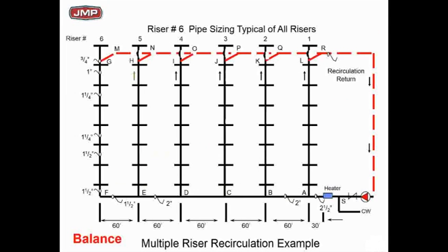So here's a piping chart for that. You see we've got risers, a water heater on the right-hand side, and a recirc pump. It's been sized, the recirc pump's plenty big, no big deal. Recirc line, but I hope you quickly realize there are no balancing valves. There are no balancing valves at the top where the little red recirc lines tie in. And this is direct return piping.